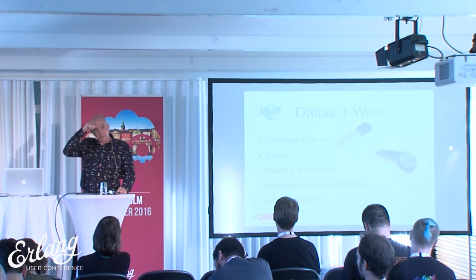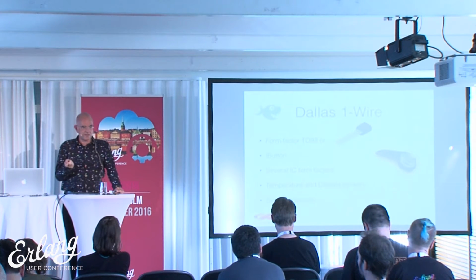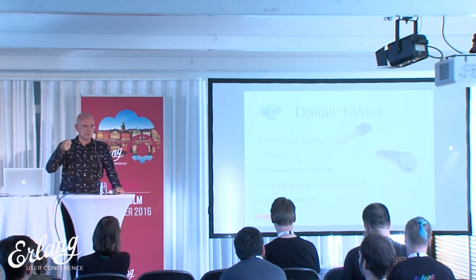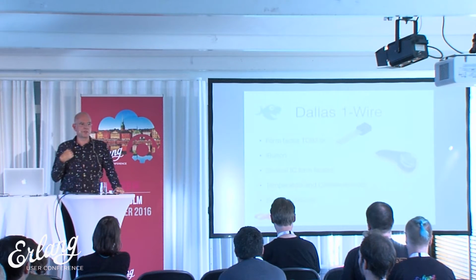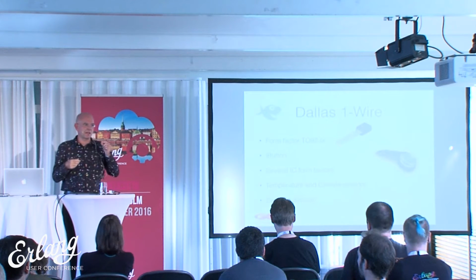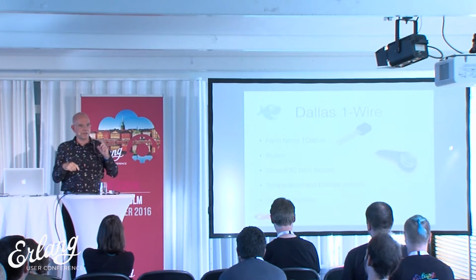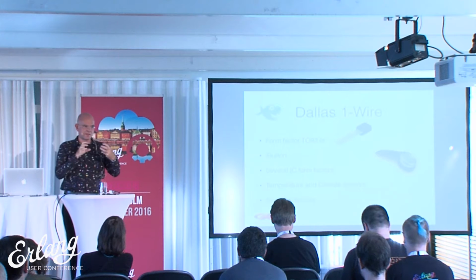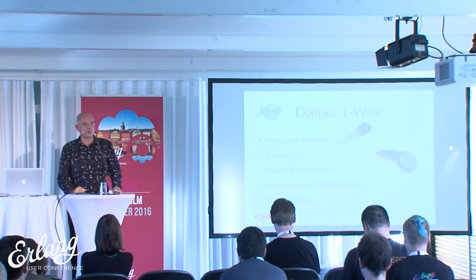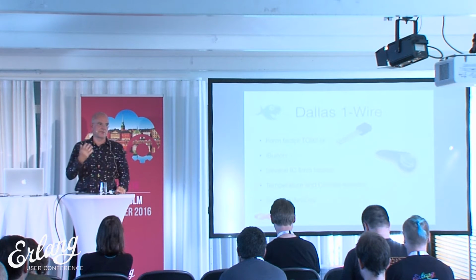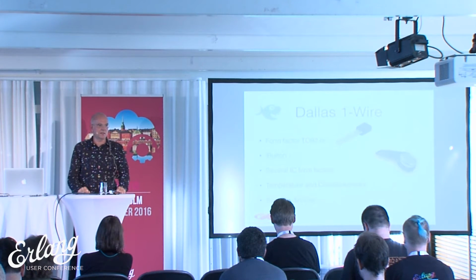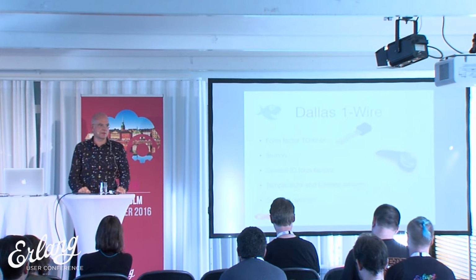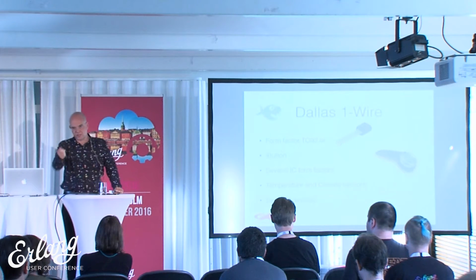There's also the iButton, which is basically a one-wire device in a metal button, which is very robust. It looks like a battery, like a clock battery. You have two contacts, one on the outside and one in the middle, which are actually contacts for the opposite side. It has a standard form factor and is used for access control, as a kind of predecessor to RFID, but it's still used. I think the Turkish public transport system uses one of these buttons, on a key fob that you just put in.